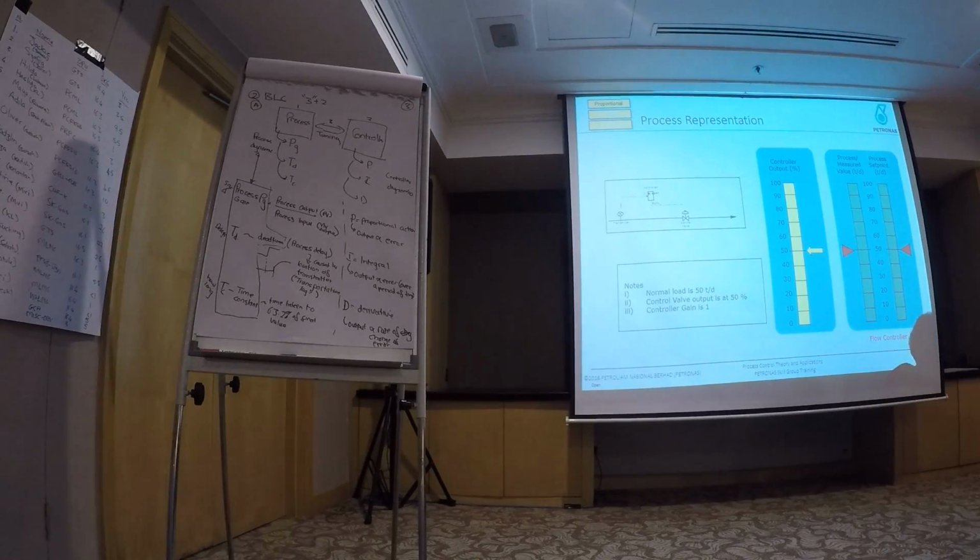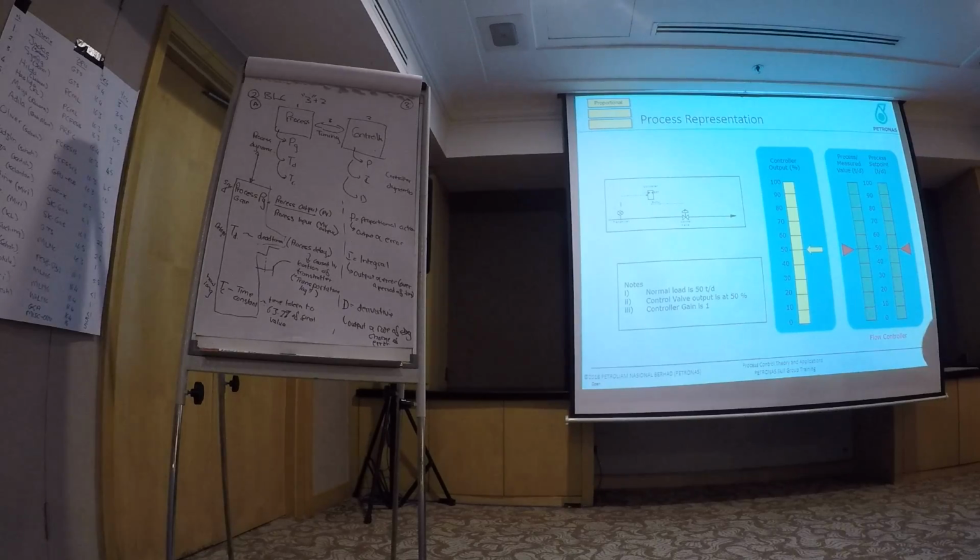You have minutes, so it's actually minutes per repeat. But in a DCS you'll see minutes. And this is for Foxboro and Honeywell. But if you go to Yokogawa, it's in seconds per repeat. Yokogawa, in seconds.